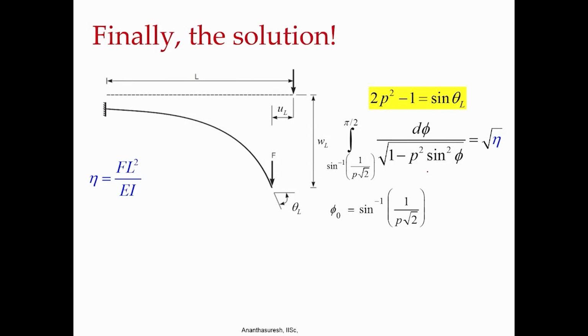So, we actually have a solution now, because we converted the differential equation that we had and that scalar equation with the no stretching assumption, we convert it into an equation that looks like this, where this η, which involves force, length, Young's modulus and second moment of area, all of these things are captured in this η here. If I know η, I can compute here the value of p, that is called the modulus of the elliptic integral, and the p as we know is related to θ_L. So, I can get this θ_L for a given value of force.